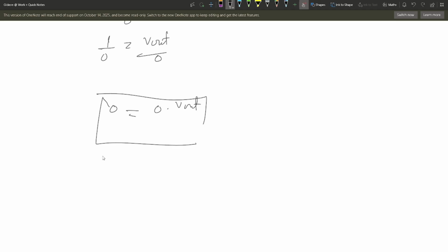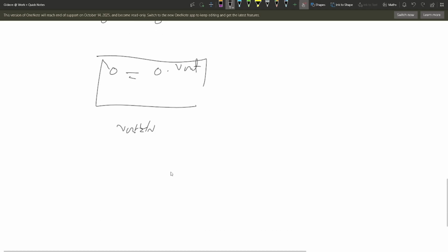Let's say V out is 4 volts, and 4 volts will satisfy this equation, and it could be any value. So we can force V out to be any value. That's what we're trying to say from there. Now this is the open loop property, or the open loop behavior, of an op-amp. Right? So now let's talk about the closed loop property of an op-amp.